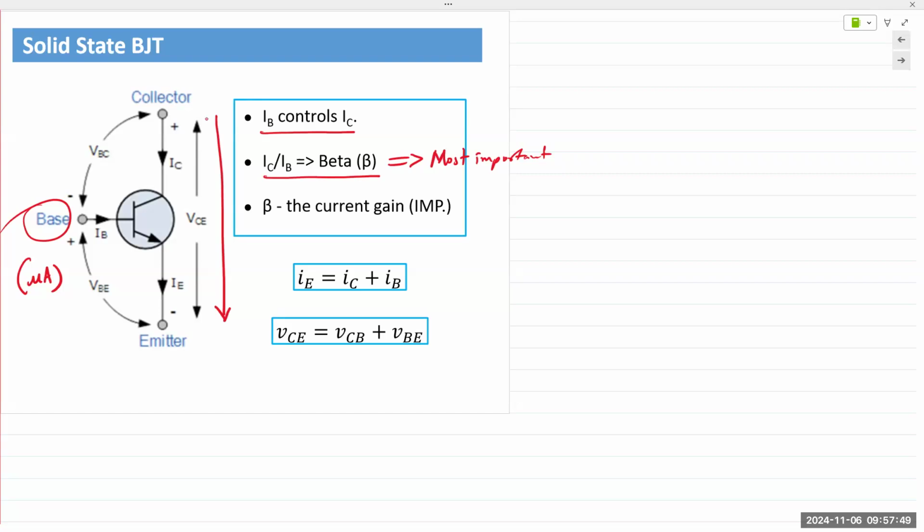So the question being asked is, how would we work with these devices, right? So the answer is yes, we can control the manufacturing process to a certain extent, but when we are talking about magnitudes of like 10 raised to 17, 10 raised to 18 atoms, we can control it down to a certain level, but not beyond that. We cannot control it down to every single atom. So if you're implanting 1 into 10 raised to 18 atoms and 1.00001 into 10 raised to 18, there's going to be a slight variation in the device.